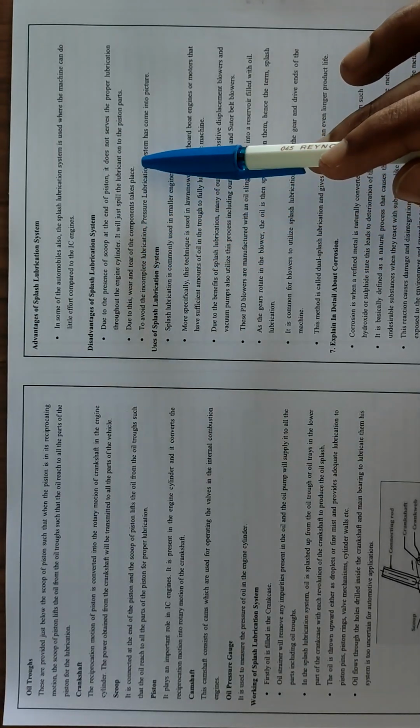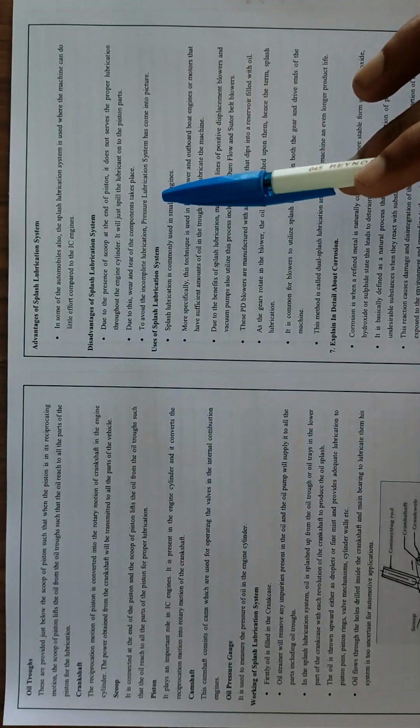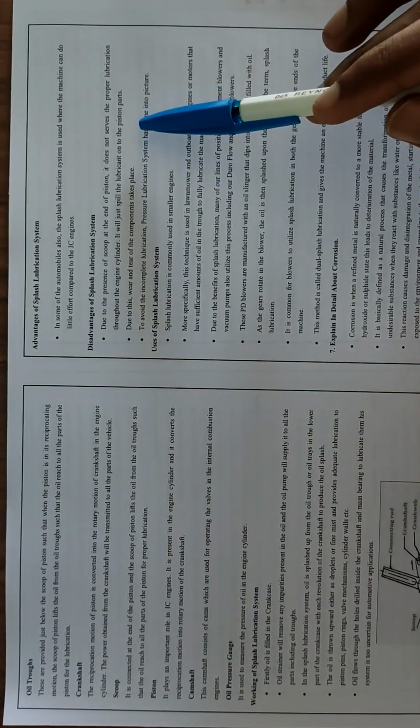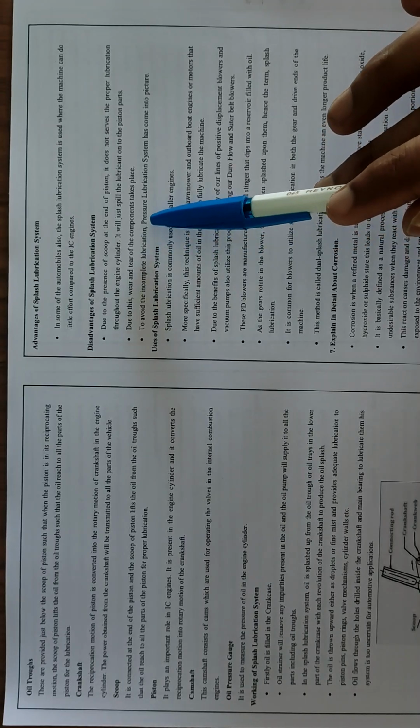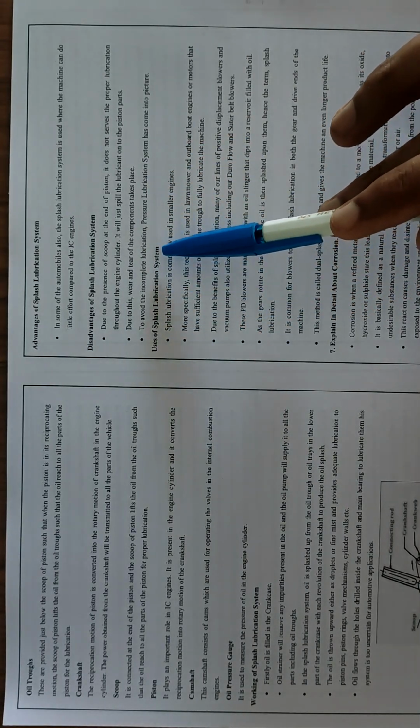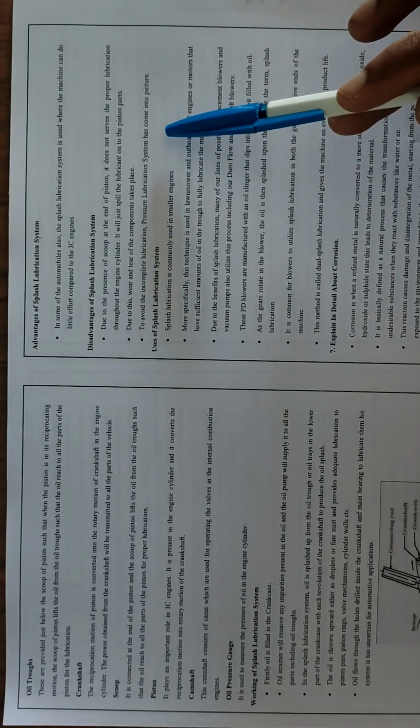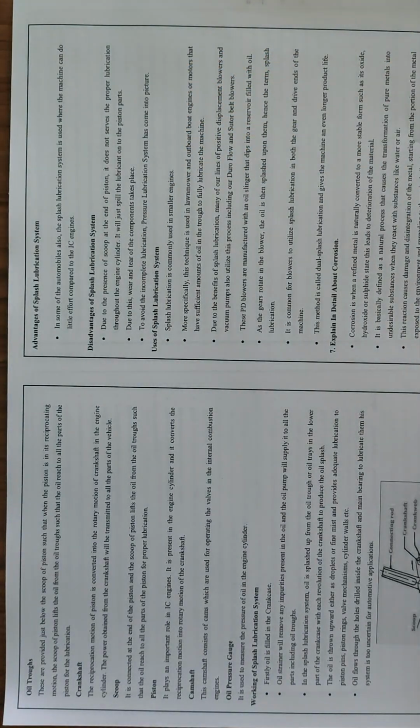It will just spill the lubricant on the piston parts. Due to this, wear and tear of the components takes place. To avoid the incomplete lubrication, the pressure lubrication system has come into the picture.